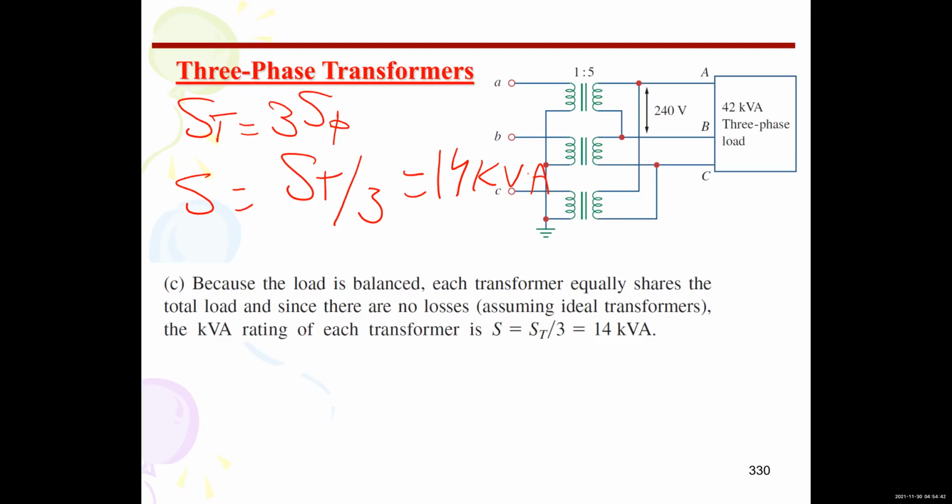So if we did an auto transformer, what happens? We get both. We have conduction, because there is an electrical connection, so part of the power is transferred by conduction and another part is transferred by induction, through the mutual coupling, which is the original one. Therefore I can use the auto transformer to raise the power transfer capability. We called it the power rating advantage. The auto transformer could be higher than the ideal transformer, with the same number of turns and same everything.